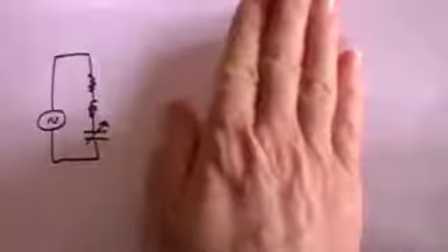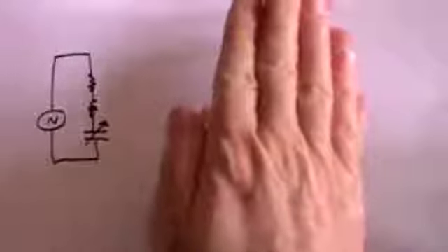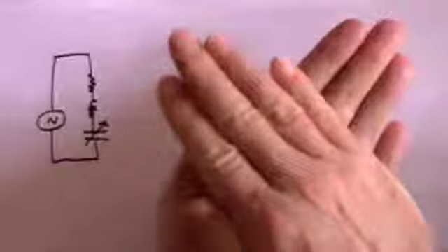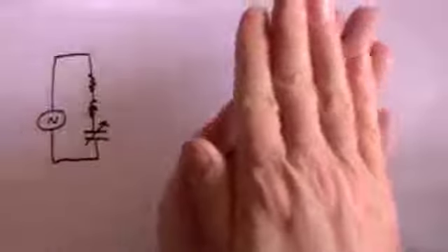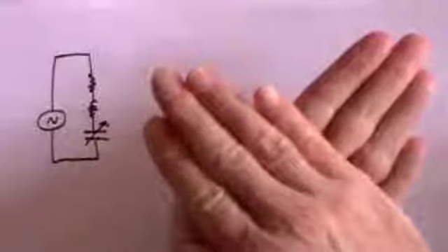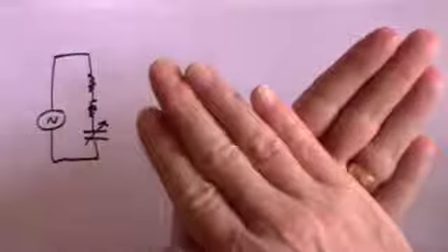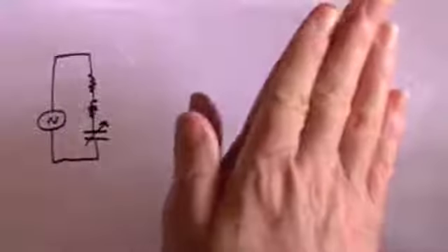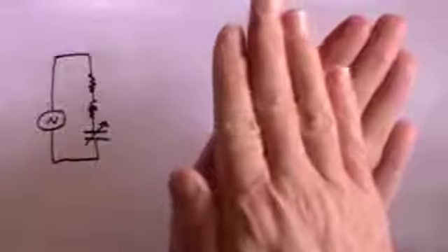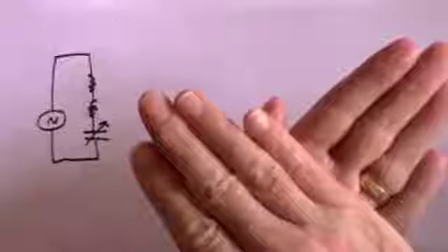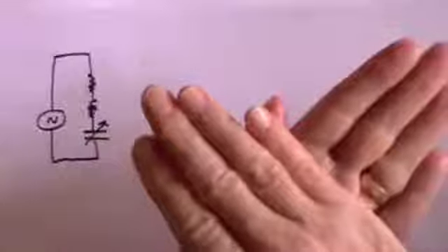Now I turn it edge on, and as you turn the dial on your radio, what you're effectively doing is turning one plate against the other, and therefore the degree of overlap, the amount of area that is common to both, reduces or changes, and that of course changes the capacitance. So the way you change a capacitor is you swivel one of the plates so that the amount of area that is common to both reduces or increases as you turn it, and that therefore becomes a variable capacitor.